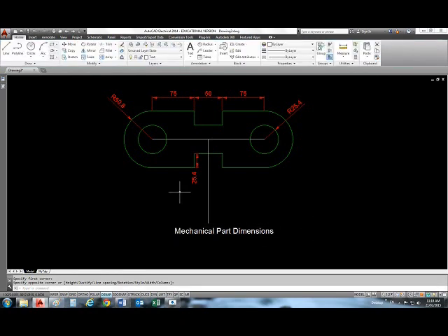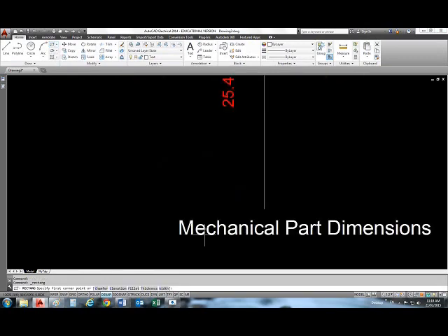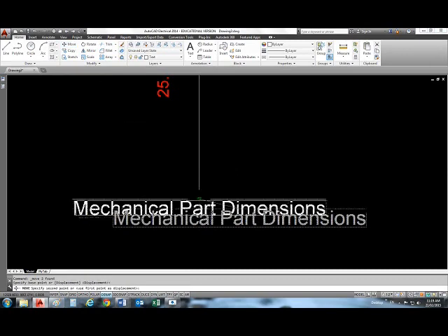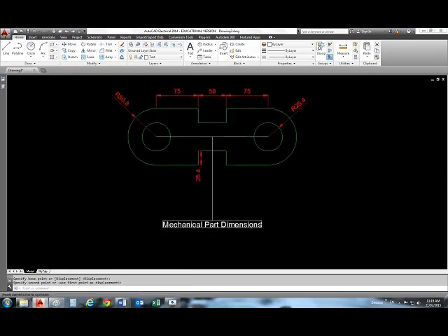Click outside. Now take a temporary rectangle from one corner to the other corner and choose that rectangle with the text, and then move command from the middle to the end of this line, and it is now set very nicely.